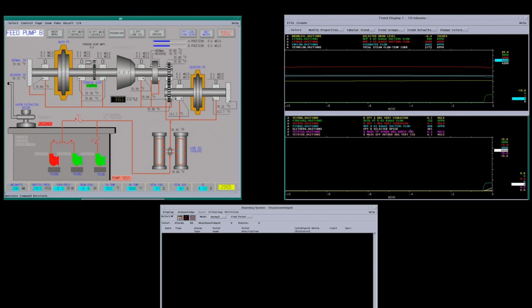On these graphs, we've listed the booster pump flow. We've got the main feed pump flow, we got the speed, and then we've put on various vibrations. It's kind of a good idea to track vibrations and different parameters when you're starting up equipment.